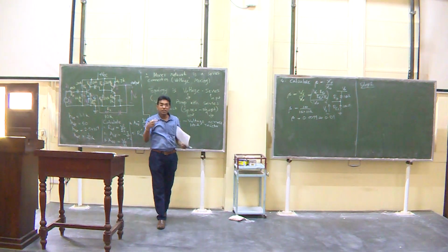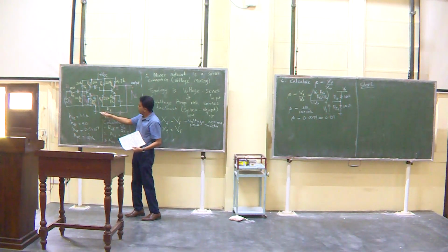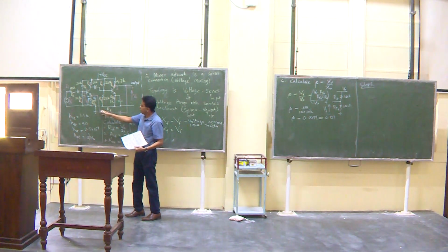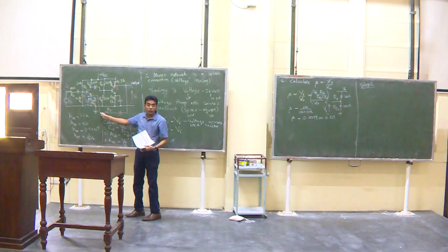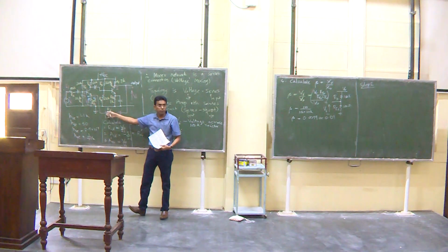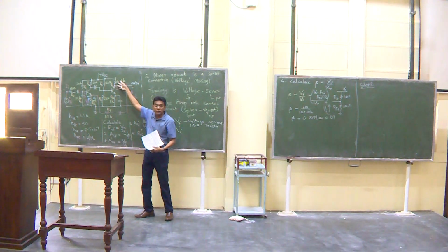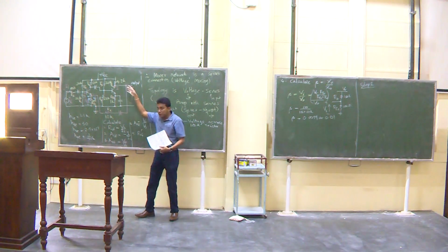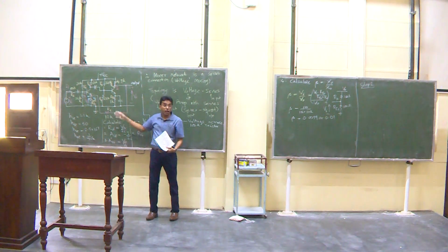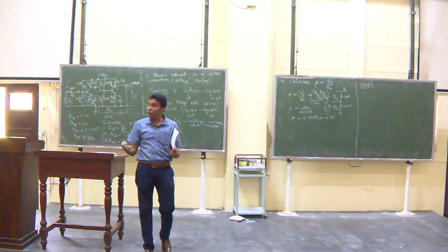So, therefore, the impedance changes. For example, if you look at it from this side, and let us say this is connected to some other ground, then what you have as the output impedance is not what you had earlier. It is in parallel with this one. So, therefore, it has to be different now, right? It is not the same circuit that we have without it.